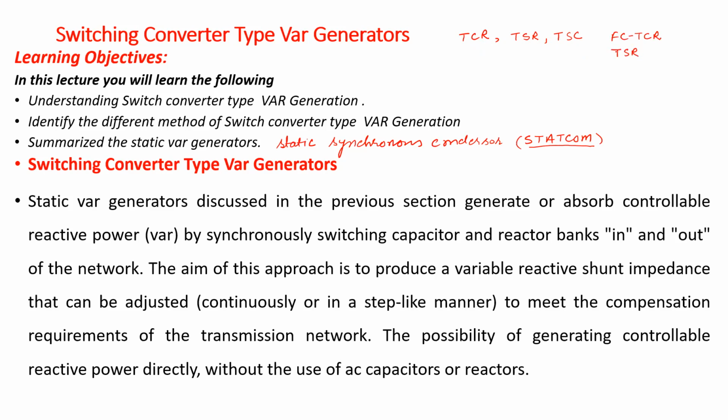That means a number of capacitors operate in a step manner, and smooth control is done by the thyristor controlled reactor. The thyristor valves switch synchronously with the system, connected either in series or parallel.